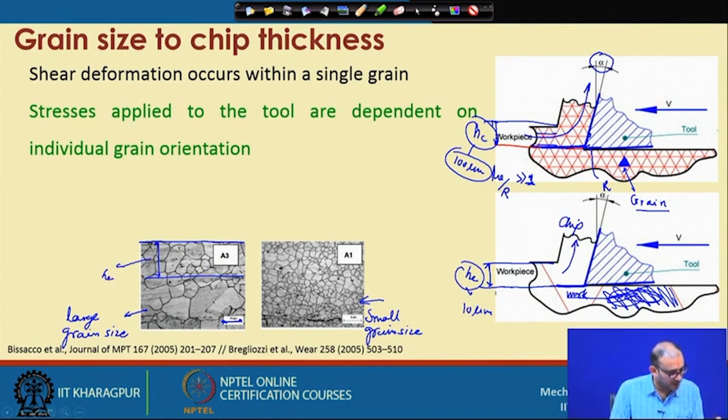At that time there are many layers, comparatively less, but you may get at least 1 or 2 layers of the grain which will come out as a chip, and that will be even easier in this particular case, because your HC will be this much, same HC, but you will encounter many types of grains. So getting that particular boundary is very easy in this case.